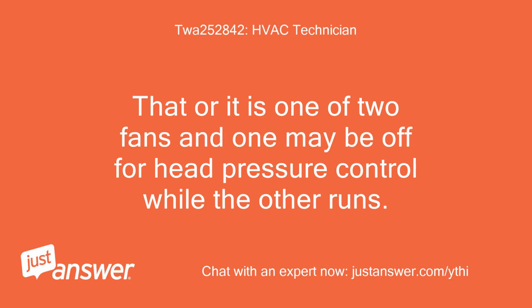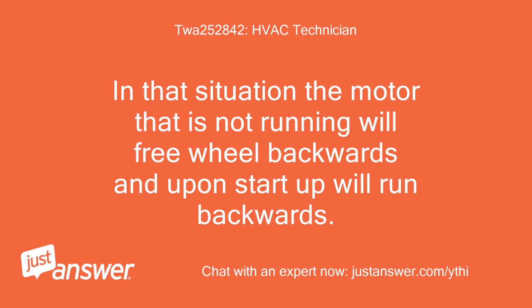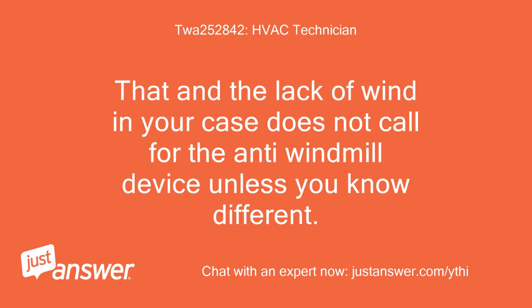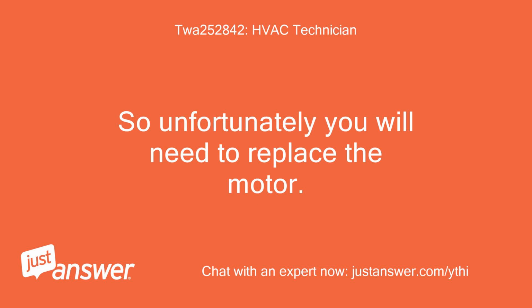That, or it is one of two fans and one may be off for head pressure control while the other runs. In that situation, the motor that is not running will freewheel backwards and upon startup will run backwards. That and the lack of wind in your case does not call for the anti-windmill device unless you know different. So unfortunately you will need to replace the motor.